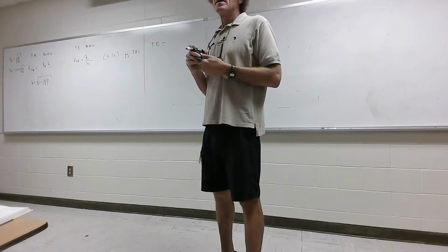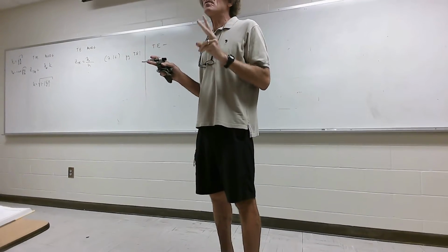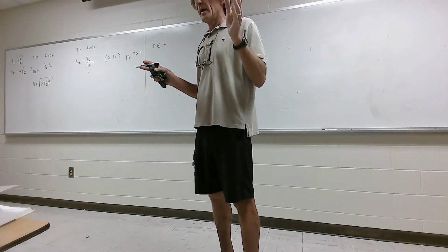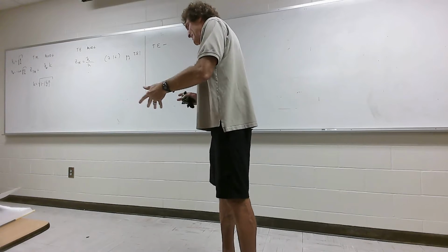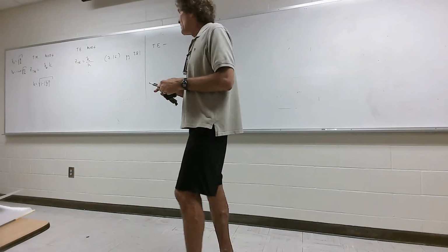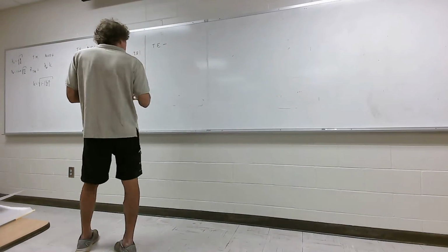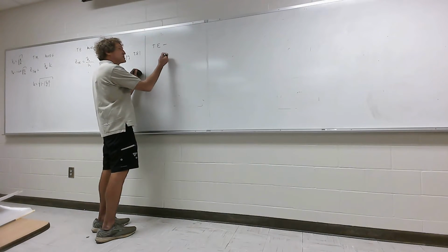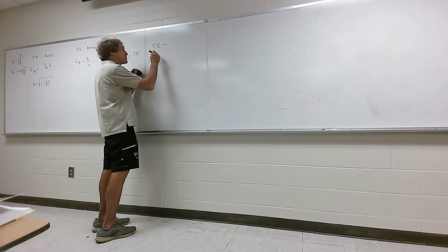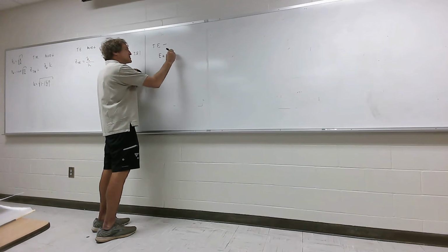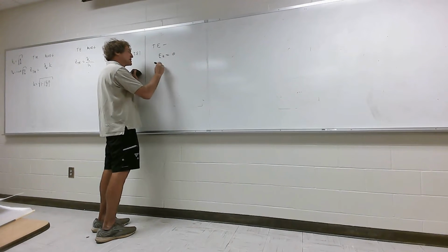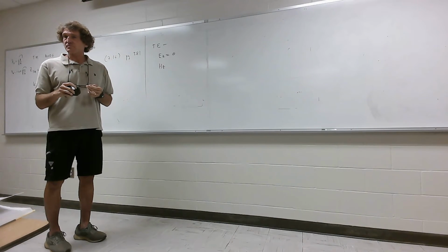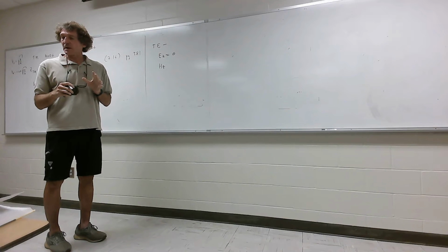So, again, chapter 7 waveguides covered the TM mode of the waveguide, right? And I gave you homework which related to TE and TM. If you did the reading, you won't have any problems. So for the TE mode, you find out that now you're basically saying transverse electric, or Ez now, is 0, and you only have an Hz. Now, when you go through these equations, I want to just say one thing.